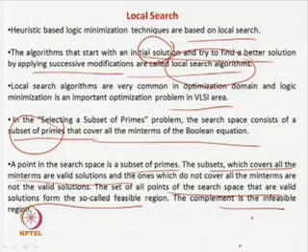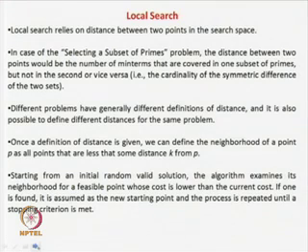There will be different subsets of prime implicants possible, that is a power set. The subsets which cover the min terms form the valid set, and the others form the invalid set. Now, you have to keep on searching within the valid set and find the solution whose cost is minimal. We should say minimal, not minimum, and moving towards optimality will take more time. If you give more time, you are going to find better and better solutions.